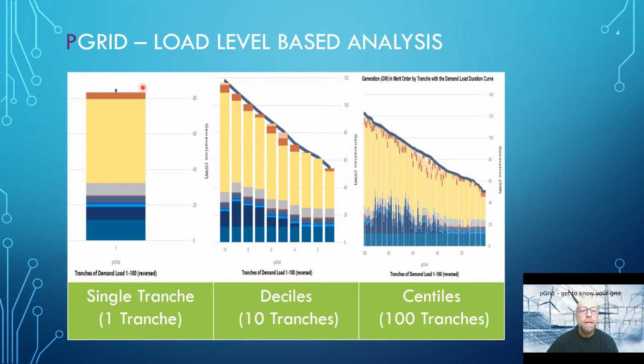This point here says, okay, we've just assumed that there's the same level of load throughout the year in 2050, that there's no difference between night and day, summer and winter, weekends, business days, etc. And if it was just one level of load for the year, it would need 84 megawatts, that is. And that 84 megawatts would run all year long and produce, in fact, the amount of energy that we actually need in the year.